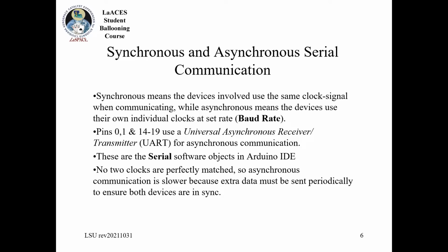Asynchronous means that there is no clock signal, but you still need some sort of standardized rate between the 2. Each device has its own clock, and on the count of 10, I'm going to send my next data, sort of thing. That's actually what that baud rate setting with the serial library that we've been using does. You're setting the rate between individual bits of a transmission.